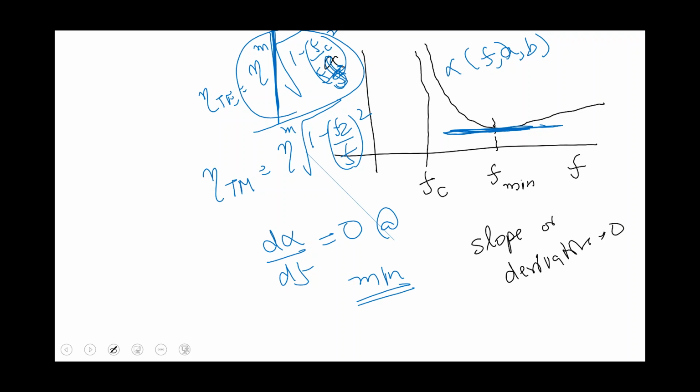So what about the value for Rs, sir? For instance, Rs you can assume to be independent of frequency. I mean Rs does change with frequency. However, within the operating range, it doesn't change so much. So you can assume it to be.